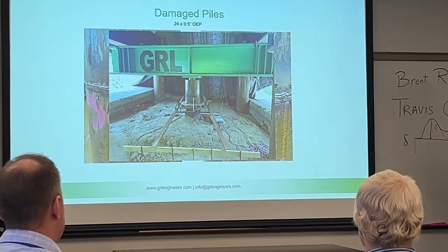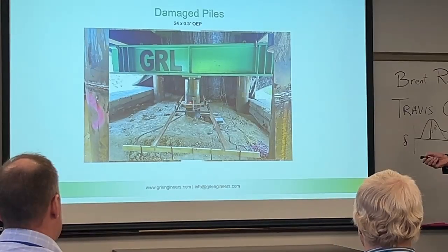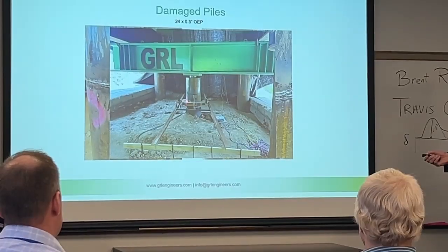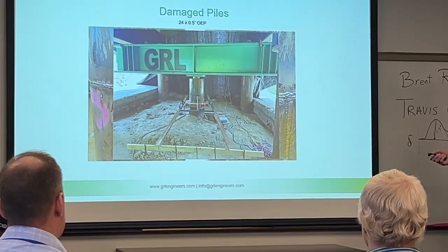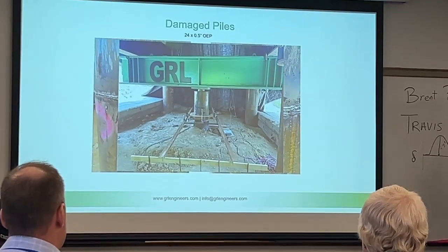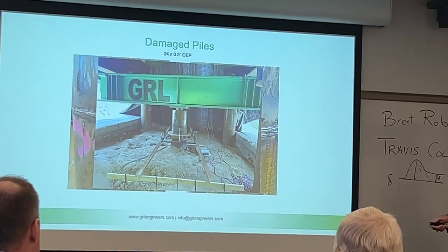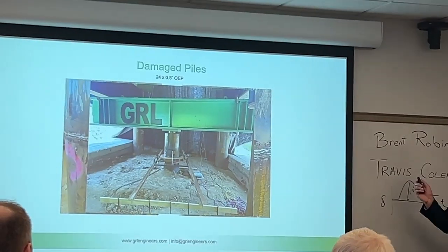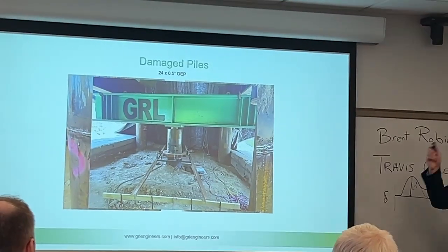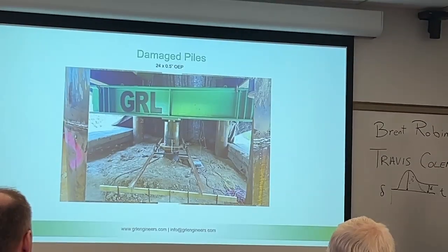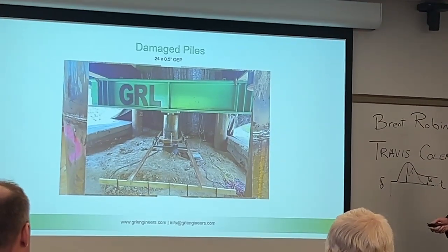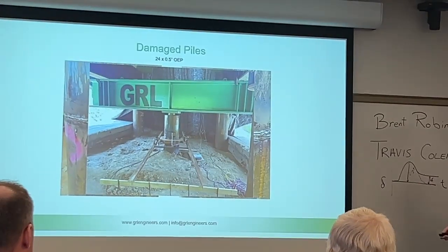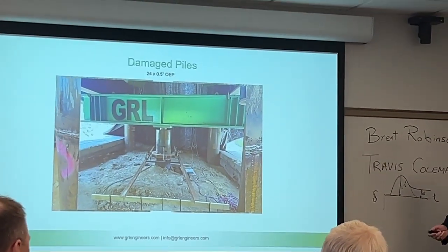So what you can see here is we cut off a piece of pipe and we welded it on to this base plate. So our entire jack stack is protected in that pipe section. We just have a cutout in it so we can see what's going on in there. But the danger would be if a splice gives, everything shifts, and our jack and load cell and everything gets thrown one way or the other. So this is the solution they came up with to protect all of us during this load test.